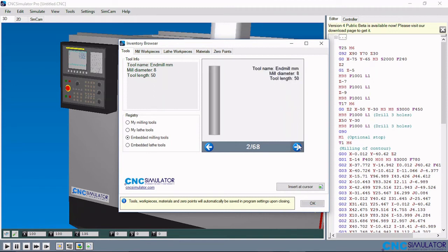And also for other kinds of tools that are available, the drill is 8 mm diameter, the tip angle 120 degrees. The tool length, depending on the profile that is to be obtained on the workpiece, will determine which tool should be used.